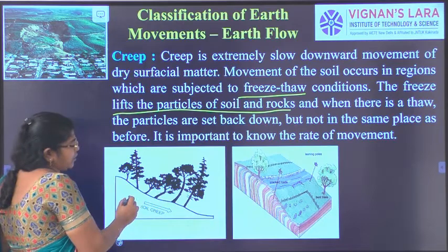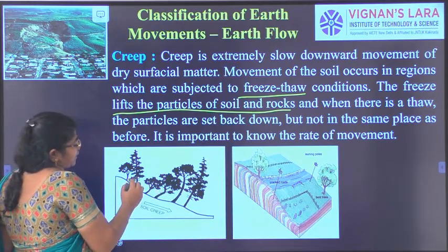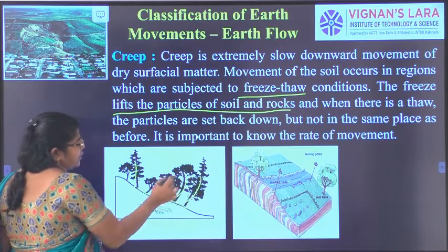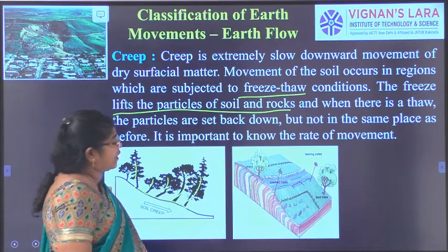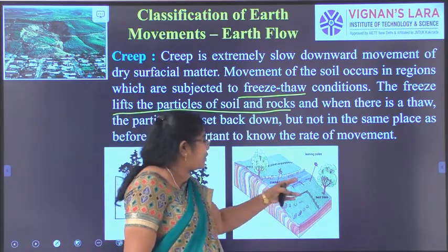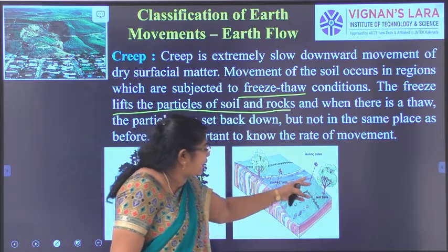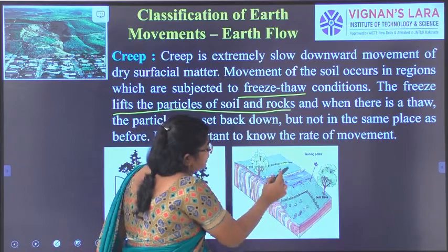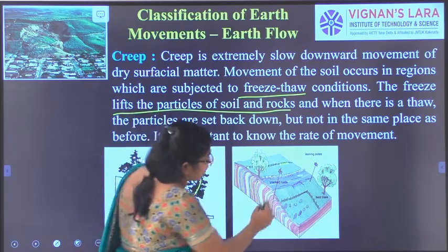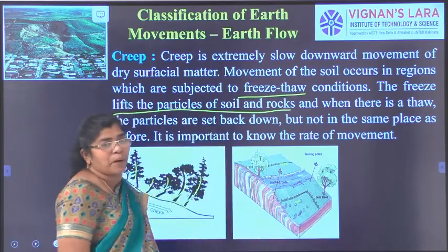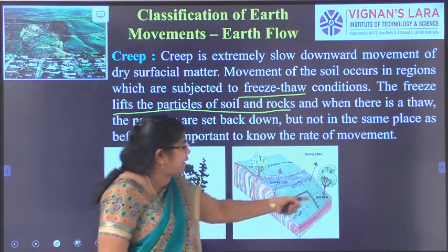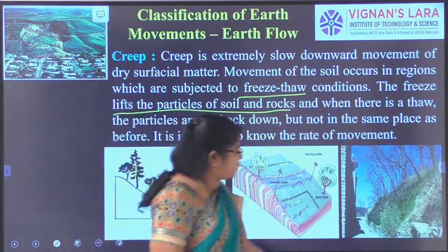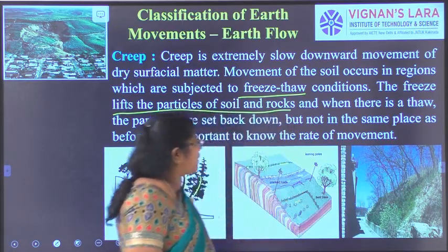You can see here the soil creep. You can see this is not a creep area. This is the creep area, where you can see that trees are bent. Okay, so the tension cracks in the road, the leaning poles, and this fence was not proper, it is curved, then the bent tree. Everything tells you the creep is there. You can see here, this is the original creep.